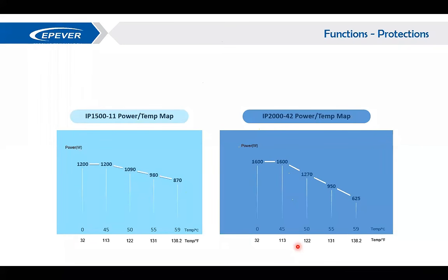So they also suffer from power losses and damage when the temperature goes high. As the inverter works to convert the DC power to AC power, it generates heat. It's natural, and this heat is added to the ambient temperature of the inverter and its enclosure. The inverter dissipates the heat through fans, or at least tries to, and the heat sinks help to dissipate this heat, but it's not always successful.